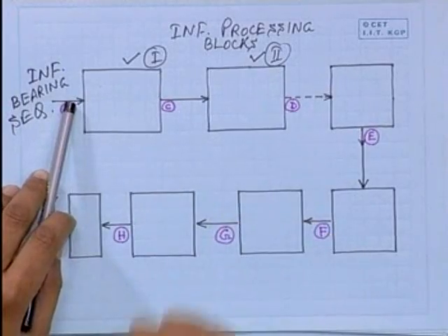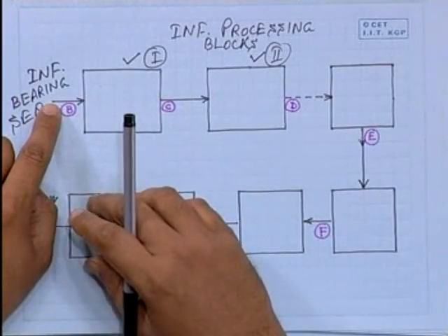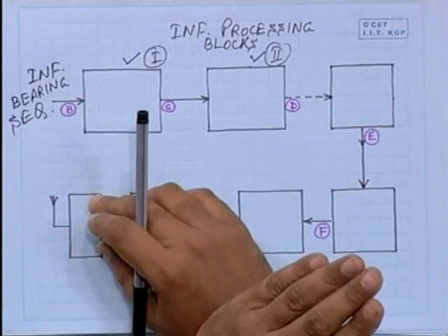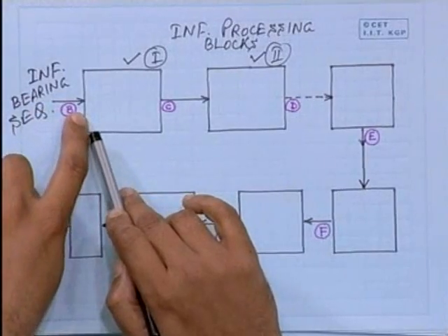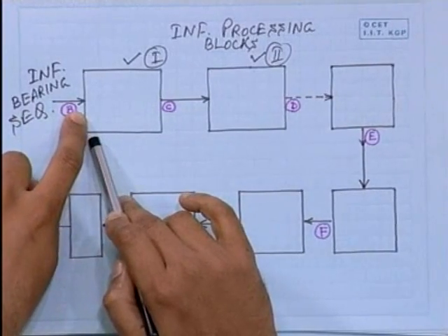So, if I think about their binary representation where each sample is represented by 8 bits, then for two samples there will be 16 bits coming one after another, and these two groups of 8 bits will vary only in the LSBs, second LSBs and things like that usually. That is because of strong correlation. So, at this point there is another possibility. One possibility is to exploit this correlation such that the bit stream that comes at this input point can be made of lower rate.